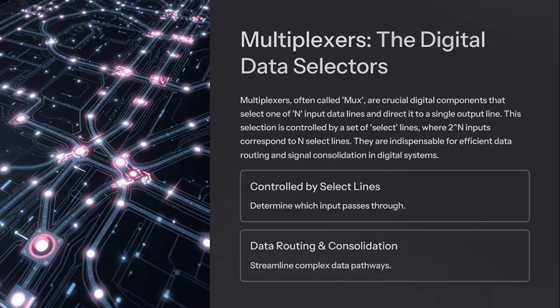Multiplexers, often called MUX, are crucial digital components that select one of n input data lines and direct it to a single output line. This selection is controlled by a set of select lines, where 2 raised to the power n inputs corresponds to n select lines. They are indispensable for efficient data routing and signal consolidation in digital electronics.